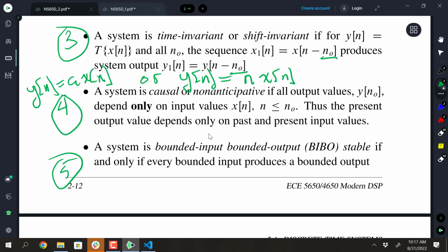The idea was to predict the channel so that you could downshift the data rate to still maintain reliable communication but not have as much bandwidth. Wi-Fi does that, cellular does that to this day, but predicting the channel so that you could anticipate, I better downshift the data rate before it actually gets tough. That was what it was all about.